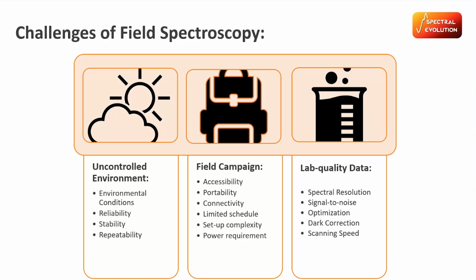When you hit the target button, it will take a dark measurement. Then it will take a quick scan and determine the optimum amount of integration time for each detector, so that you get the maximum amount of energy to each detector without saturating it. And then it will take your measurement on whatever averaging you have.